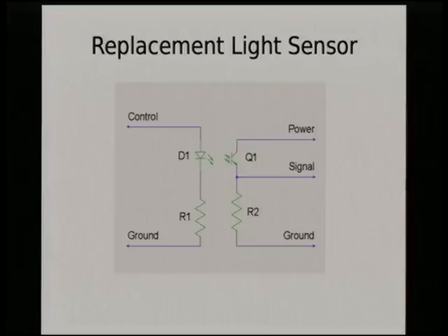I was wrong. One of the things the kids have a really hard time understanding is that if you don't turn the LED on, it doesn't work, because you don't have a lot of IR light in your environment currently. So you have to turn the light on and shine it on something and get a reflection. If I did this again, I would work harder to find ambient or visible light sensors, because it gives the kids a lot more visceral response. However, trying to get large phototransistors that respond to visible light, I can't find any at this point. They're all IR only, and they actually clip off below the red range.